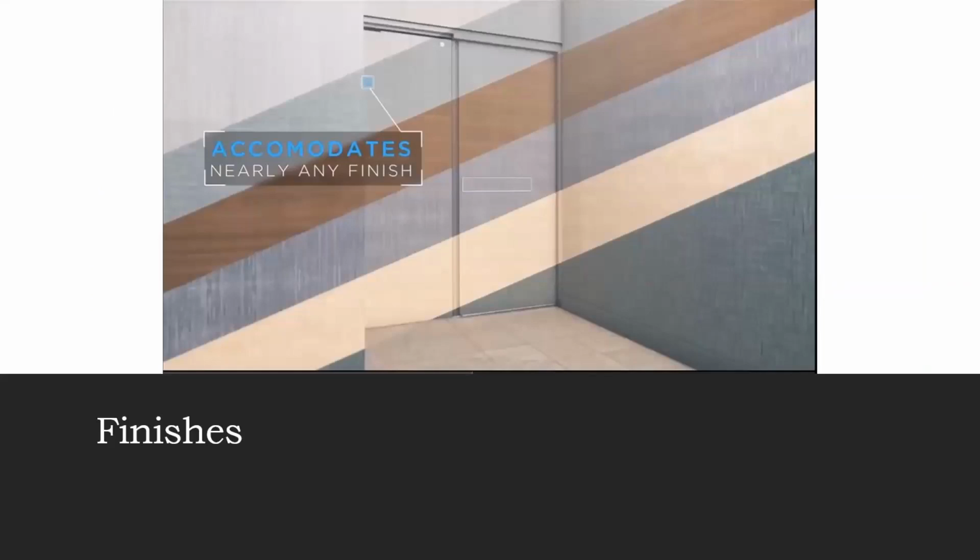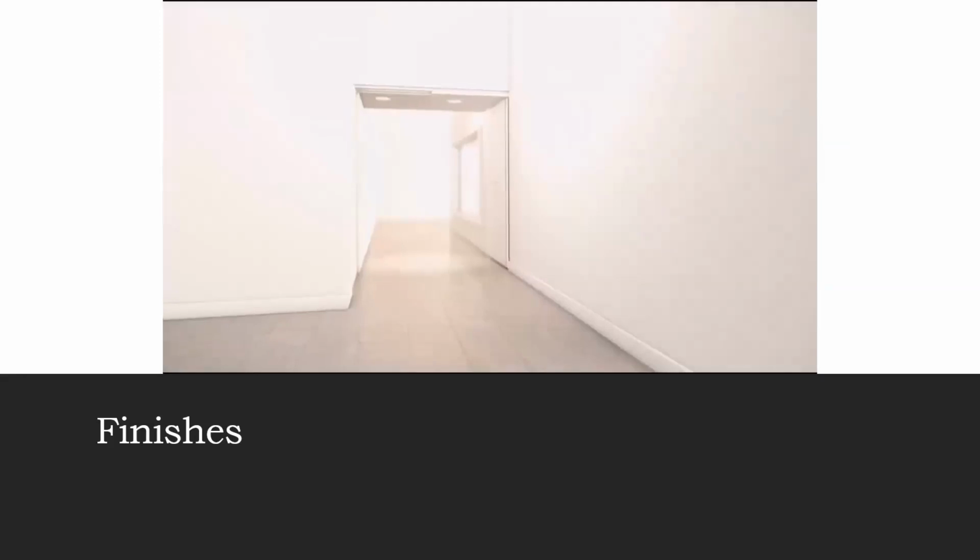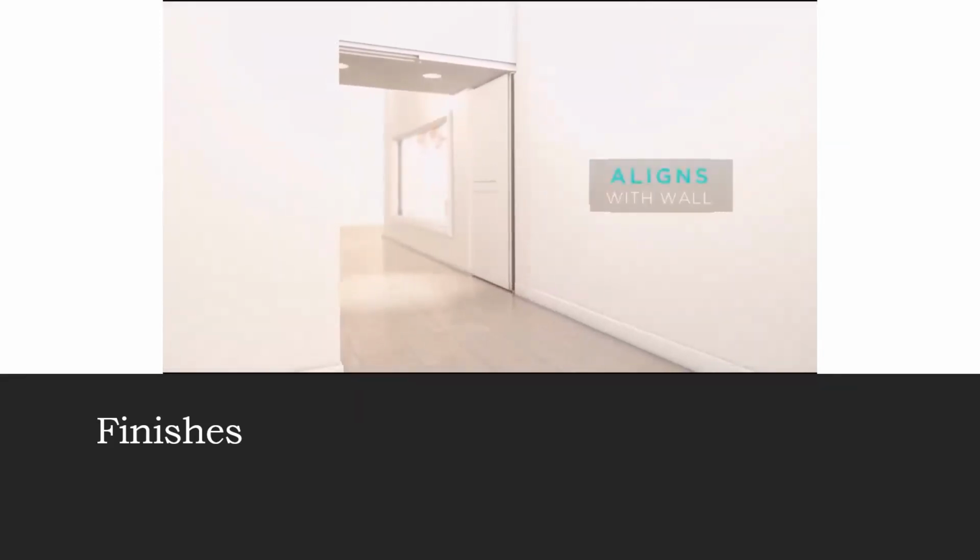Now there's many finish options for integrated door systems. Integrated door systems are tested as a complete system, and essentially we know the rating will hold up on the doors no matter the finish. So they're going to get what's called a certificate of compliance, stating that in their manufacturing facility, they can put any finish on their door, because in the event of a fire, their door will stay up for the allotted time that it was tested to, and then the finish will just come off, burn off, whatever it is. And so a multitude of finishes are going to be available.